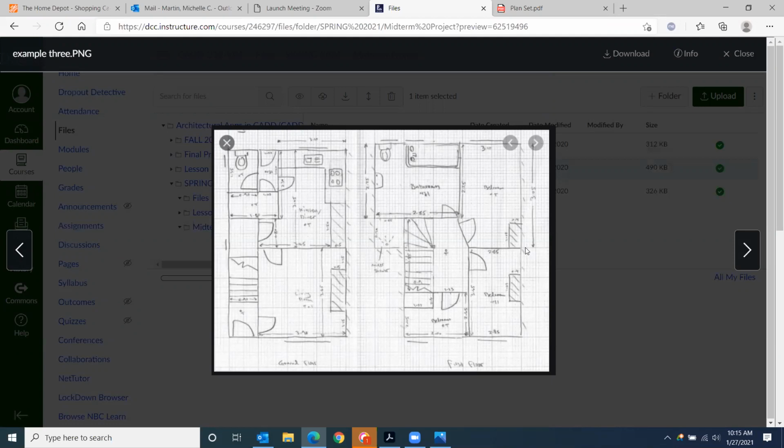When I'm just going in and doing an initial inspection and just doing my room sizes, I'll just use a single line. The important thing is more when we're doing a CAD drawing as opposed to a Revit drawing, because CAD's the one where we have to remember to put that extra wall in, but Revit will automatically do it for you. So you don't have to do the double wall thickness on there. You can do it like this.